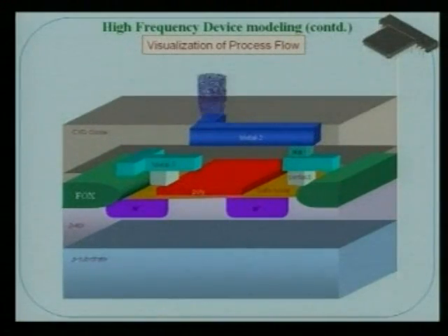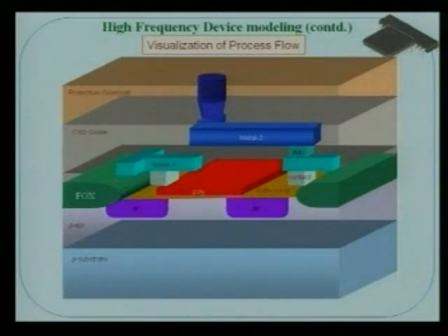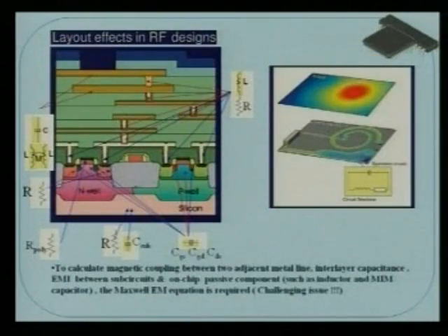And this is the metal 2 for the final contact, and then another CVD, and finally how it looks like your VLSI. So you find that in our CMOS 0.18 micron process, your epi layer is here, the MOS devices are here, the N well, P well, the gate and the poly layer. On the top you have 6 metal layers, and these 6 metal layers are basically for your interconnects, for making routing around those devices, millions of components to be connected through those running wires, and they have to be connected through vias, and these vertical lines are called the vias.